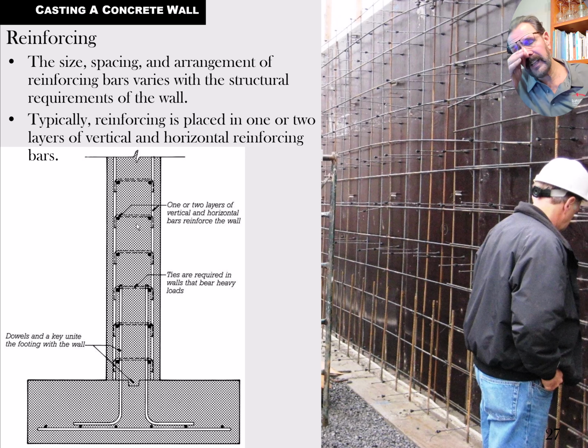You see on the right-hand side here a double mat of rebar, two walls of rebar here. And so it's a vertical mat, but it's a mat. And you also probably notice that there's some things sticking out through the form. There's one concrete form already placed there on the other side of these two mats of rebar with form ties poking through. And those form ties are ready for you to go and take the second wall form after you've got all the rebar and anything else that needs to be in that wall.